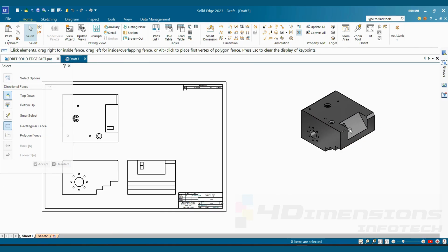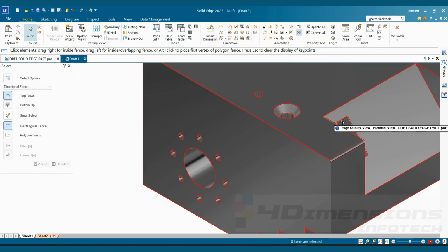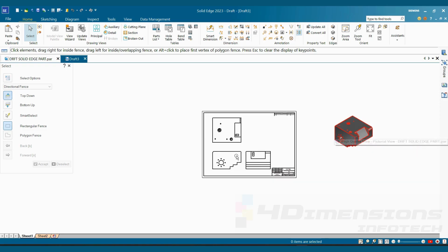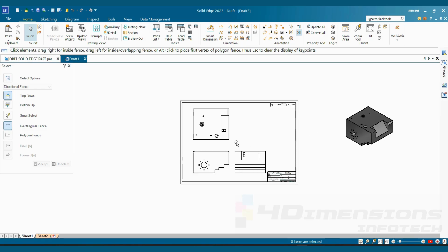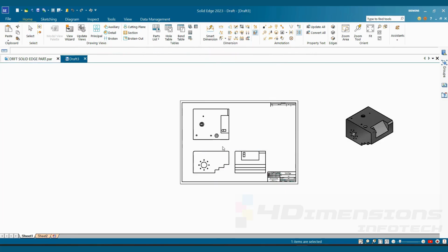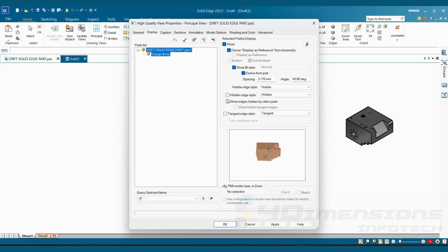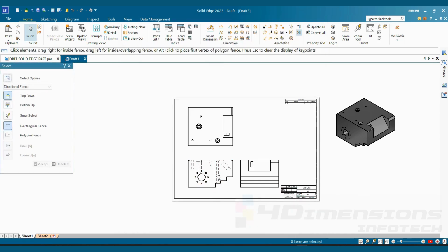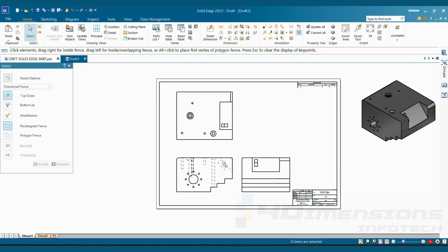So to highlight this feature in proper position so as to take the dimensions for this particular feature, we need auxiliary view. But for that I am going to click here on this front view, say right click properties, and we are going to say hidden lines visible here. As soon as I put on the hidden lines here, you can see this inclined cut here with the hidden line reference. So we'll use this inclined hidden line so as to project the auxiliary view here.